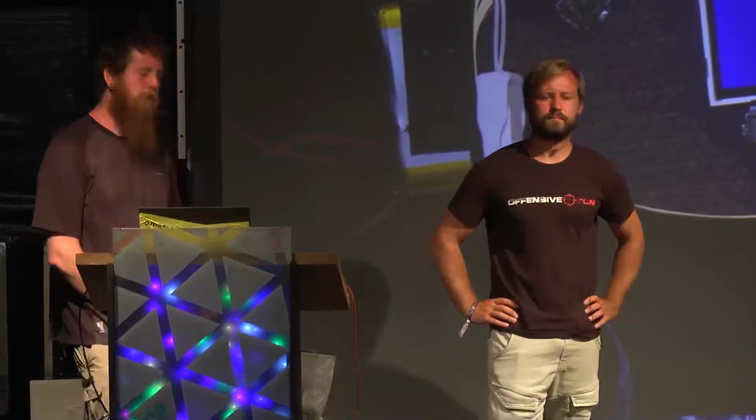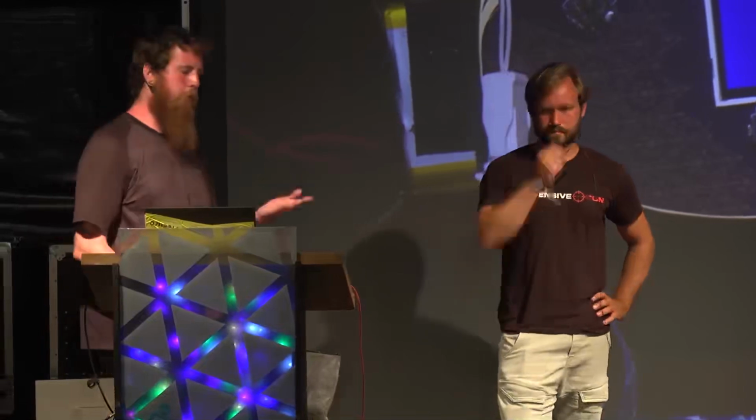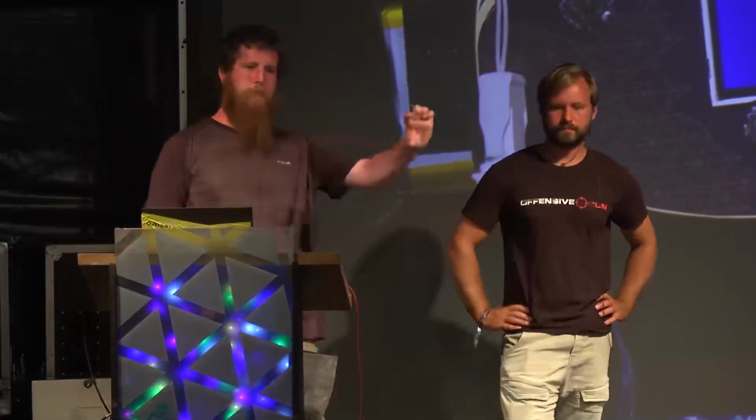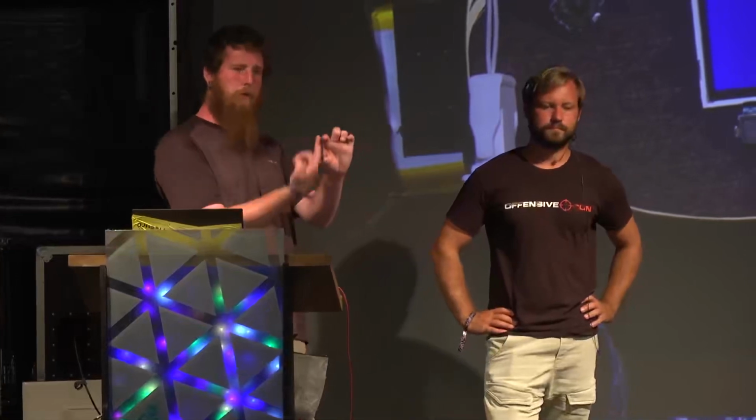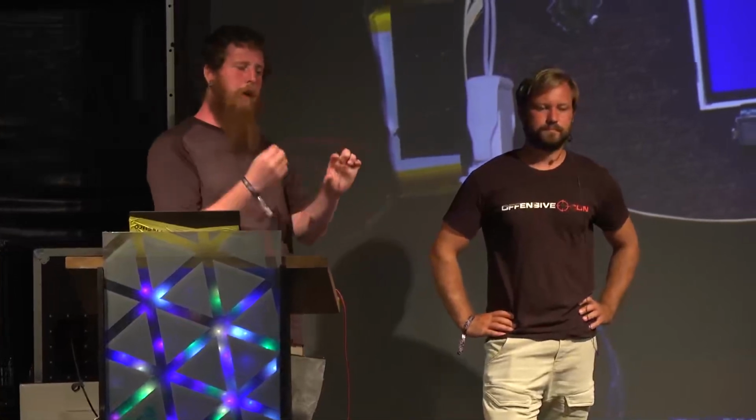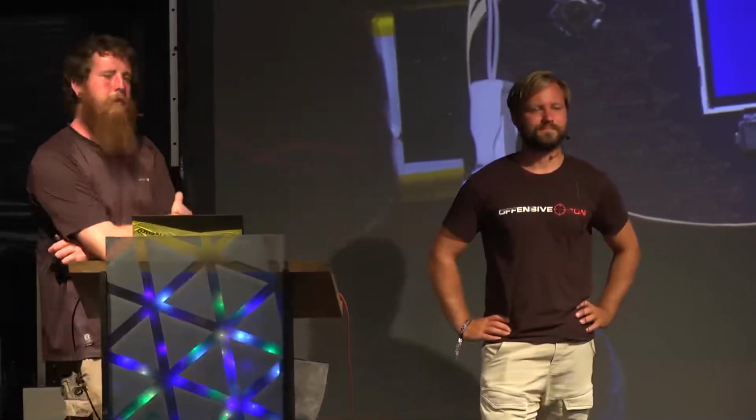Yeah, so that's mostly what we do with lasers. As I guess you know, you have your polysilicon layer, you have your metal layers above. We will usually always go through the silicon because to that wavelength of light, it's essentially invisible. Whereas if you were to try and come through the metal layers, the laser can't easily penetrate them. There's a lot of scattering, so it's much harder to do. It's possible in some circumstances, but usually it's backside. Okay, thank you.